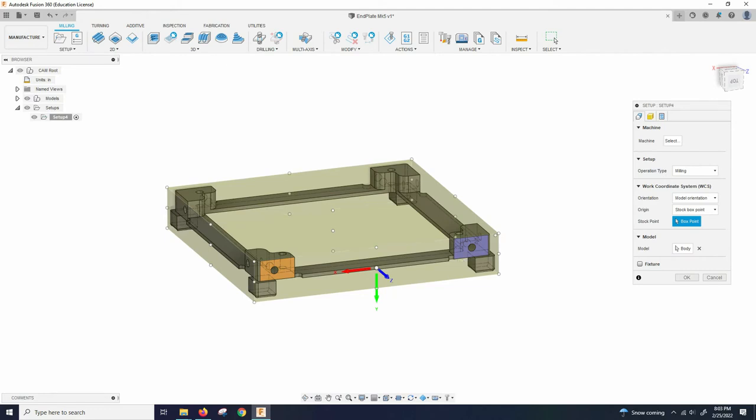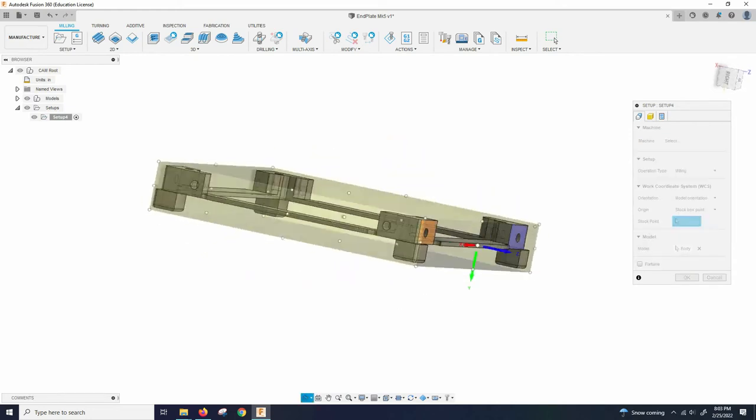A lot of times, I know when I'm designing things, I do like to have at least one plane going through the middle of the part where I know there's symmetry. It just makes your life easier to have a nice central plane that you know how to mirror across. And then sometimes maybe your top plane is a certain way or you're viewing it, but it's usually never the same.